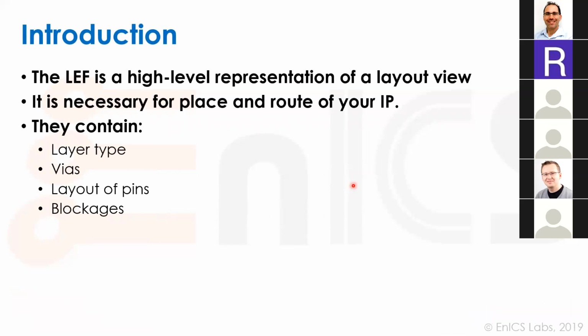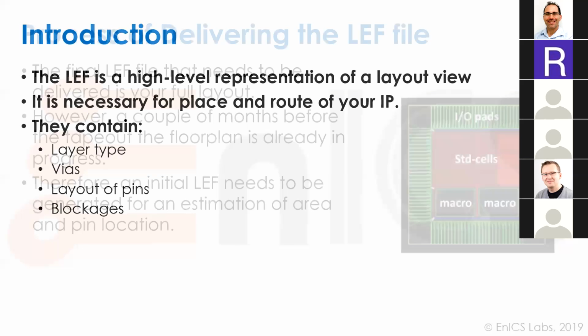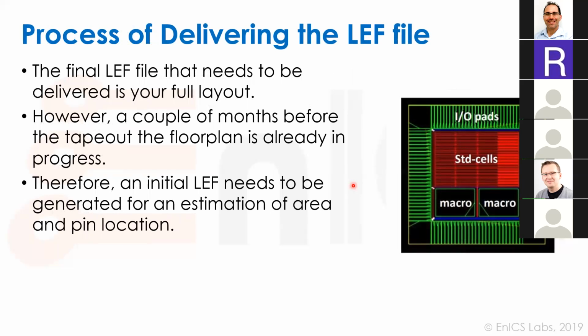So now we'll talk about the LEF, which is the most important thing. Just in a small introduction, as you remember, the LEF is just a high-level representation of the layout. This is what Slava needs for integrating our block. He needs to know the dimensions and the pins and everything. And they know what the layer types are, the vias, the pins and blockages, and so on. So the final LEF is the one after we finish our design and simulation and everything, and we finish our layout. This is what we deliver.